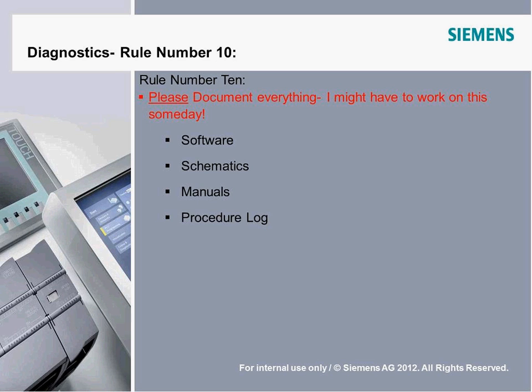So document everything. Software: any changes you made, version numbers that you saw when you got there, any differences between the software that the guy handed you and what you saw inside the machine itself. Those can be issues that come back up and bite you later. If you've changed any wiring, make sure those schematics get updated, so people that come in next are looking at drawings that are true representations of what that machine is.